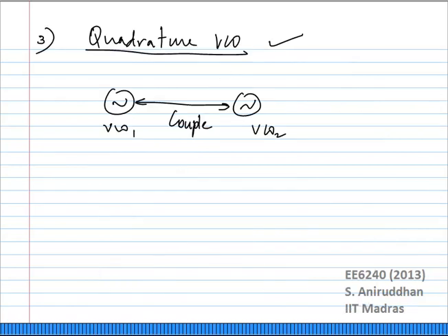Well, if you were to do that, you might as well use two VCOs. They will operate at your frequency of interest. Okay, you don't need any extra dividers, and you probably use the same amount of current or even less compared to the other one. Right? So each one of these techniques can be used with certain kinds of systems in certain situations. Okay, so that is the important thing to remember.